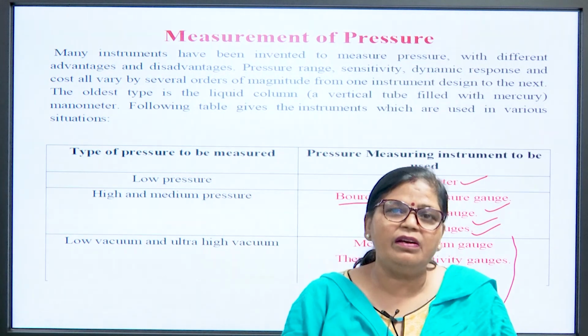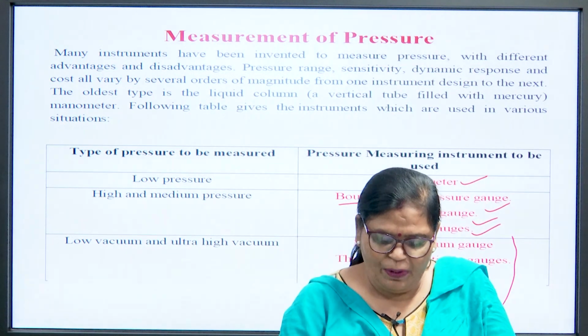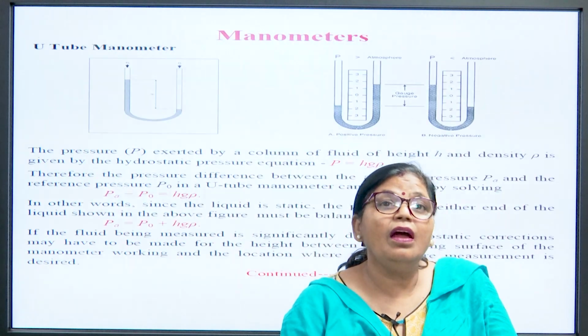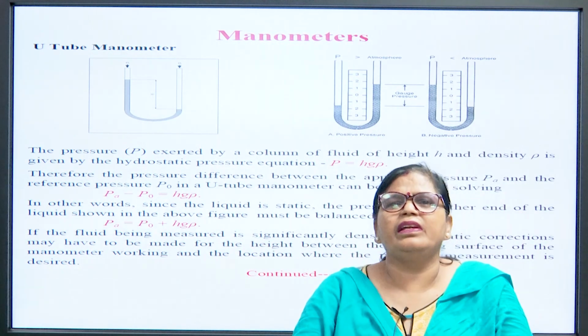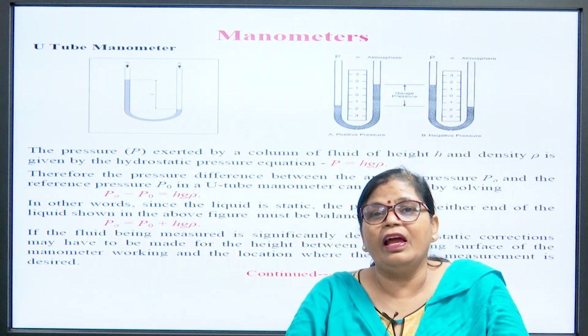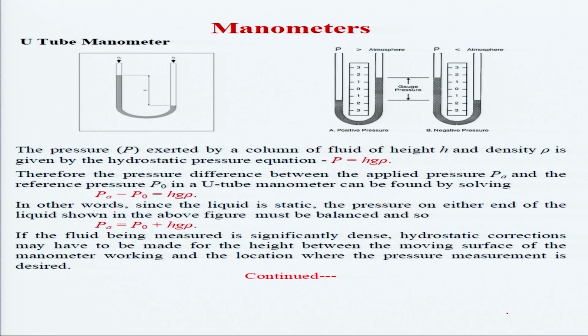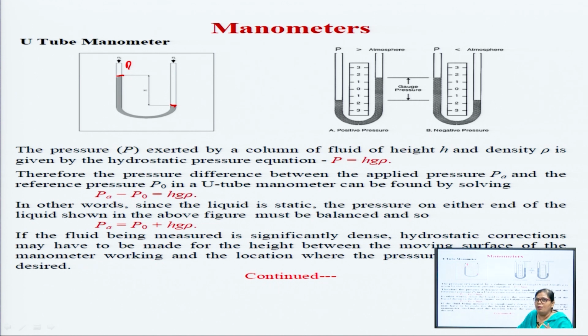This is the general purpose measurement for the low pressure and you can say the low medium pressure. तो we can consider that time we measure the manometers, where we consider inclined manometer, different types of manometers. Today we are using the digital manometers, but here we discuss only the basic concept of the manometers, U-tube manometer. So we consider the construction. Suppose this is PA, P unknown. So the difference between this and this, हम क्या करते हैं, we consider as the height और दोनों का difference लेते हैं with density and gravity. Then you can directly measure the pressure with the help of the manometer.